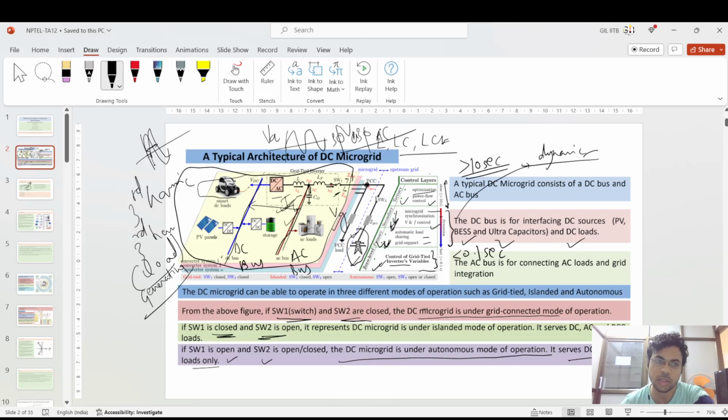So you cannot actually utilize the system, and it causes distortion in the power quality itself. So you need to synchronize the voltage generated from the inverter and the grid voltage. For that you need the voltage magnitude and the starting point of the phasor. So that is the secondary control.